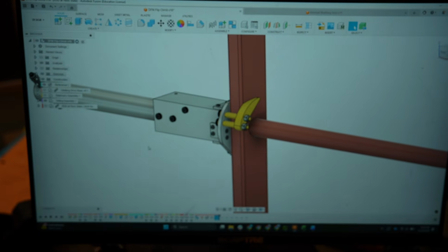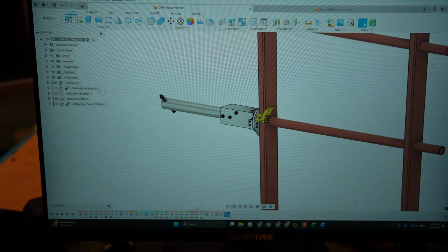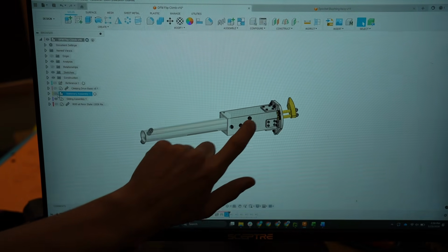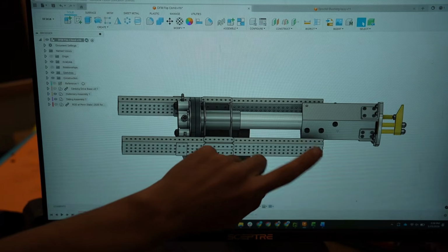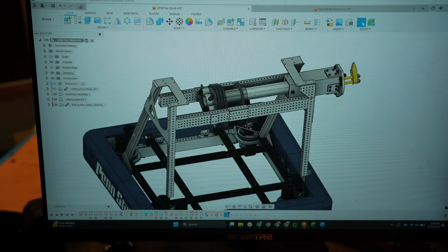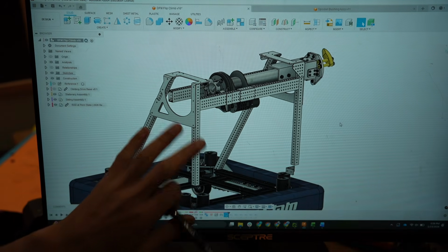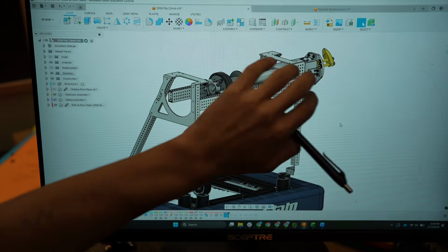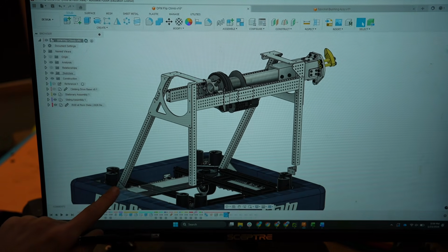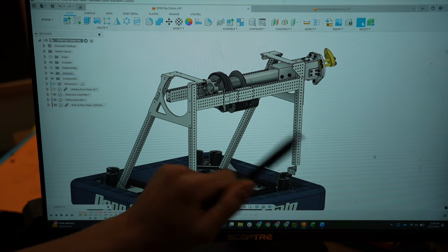All right. So I appreciate you sticking with us. We've gone through many elements of the design so far. We've done the pole, the box, the hook, the little prawn, the entire superstructure. And this is how you become confident in design, is going piece by piece, following what's called the load path from high load all the way through no load, which is like at these final attachment points. It's like 10 pounds. And that gives you faith in every part of this chain.